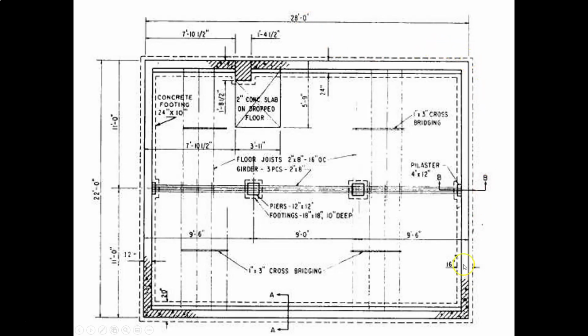And then on the same side, I'm not going to pay attention to these exact numbers, but let's say it was the same exact situation, which usually it is. This would also come over 6 inches. So while this wall is 28 feet long, this footing is actually 29 feet long. Again, that's what I mean by pulling dimension strings a lot.